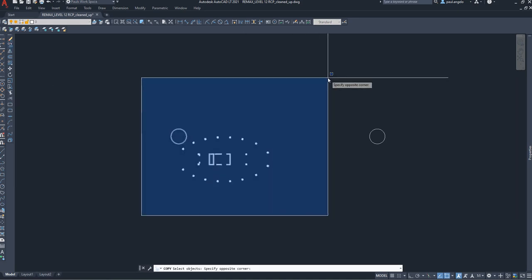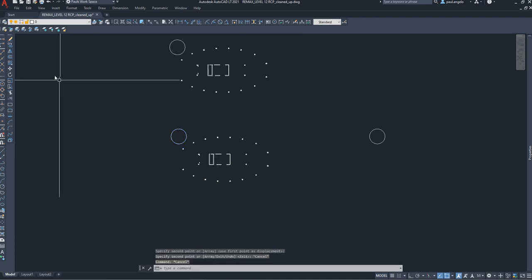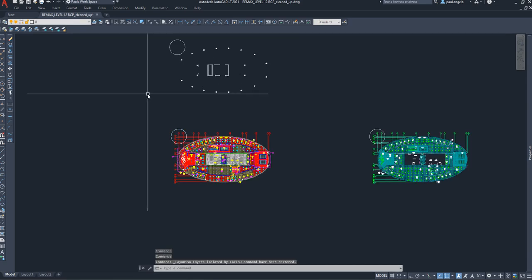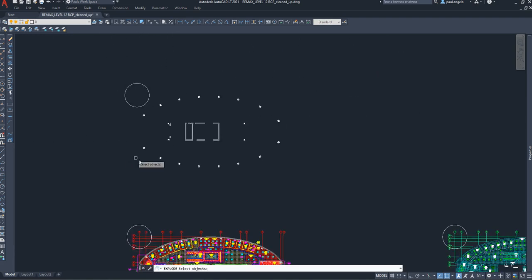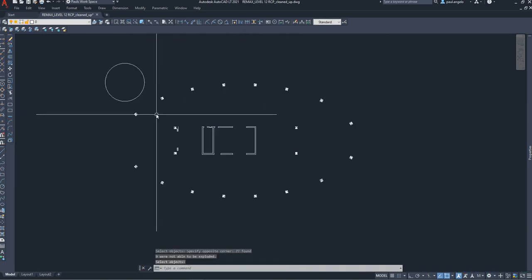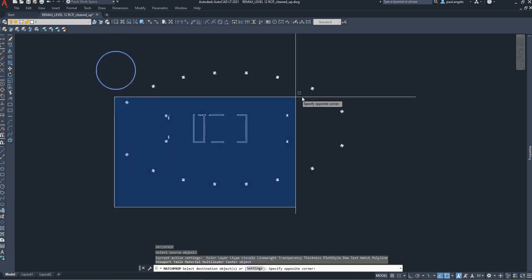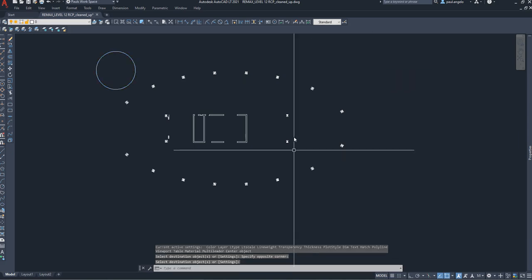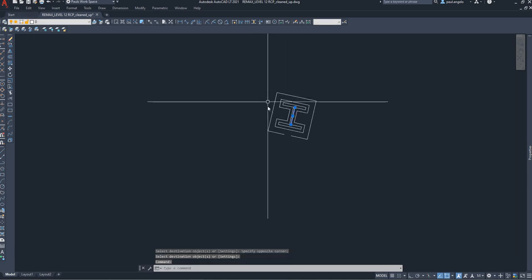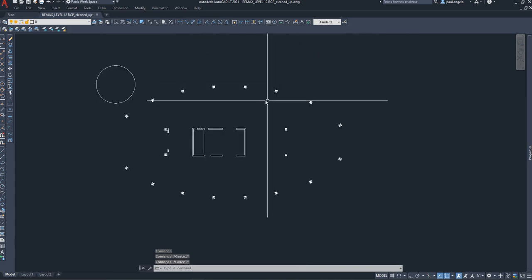Let's copy this, bring it up as we have before. Now unisolate. And okay, so now I can see everything. Let's do the usual here. Let's explode if there's anything to explode. It might be. Now let's match properties, even though it's white. I think it was on its column layer or structural layer. Let's do this. Looks like we got it. Everything is on a 0 and busted up. See, the objects are now in their individual pieces after they explode.